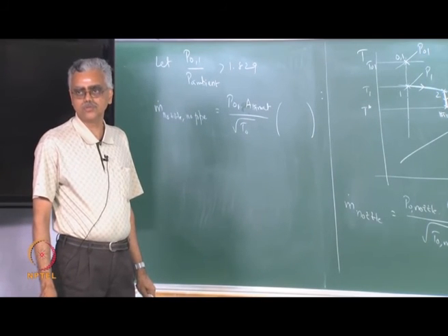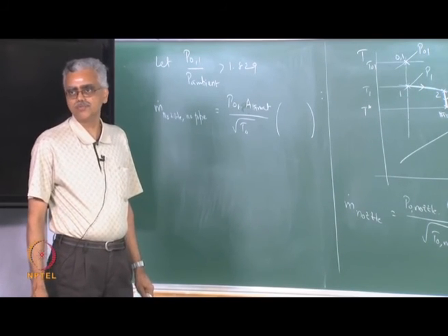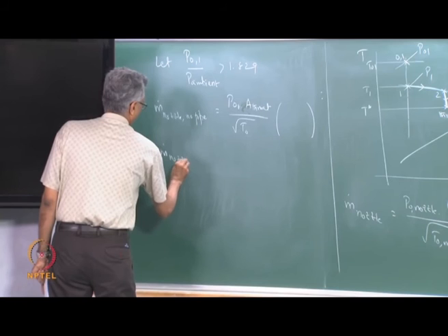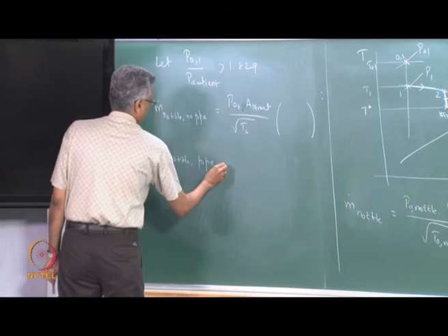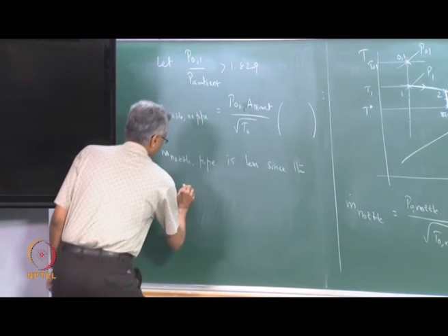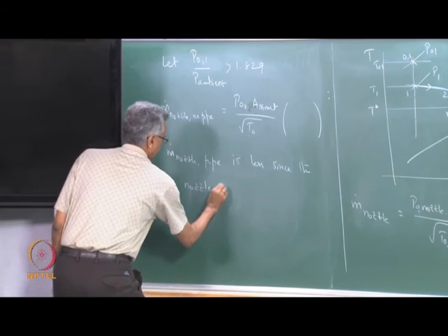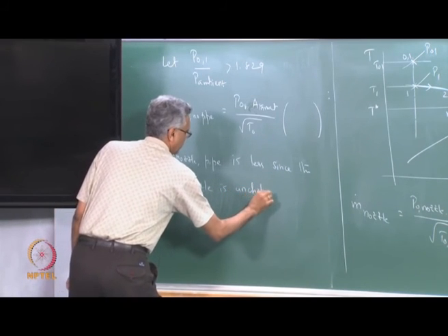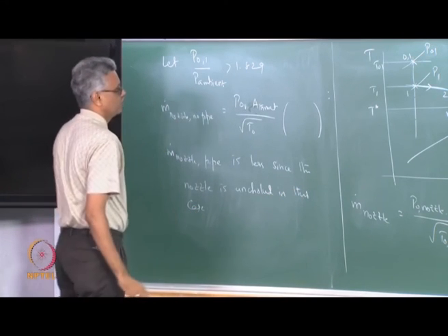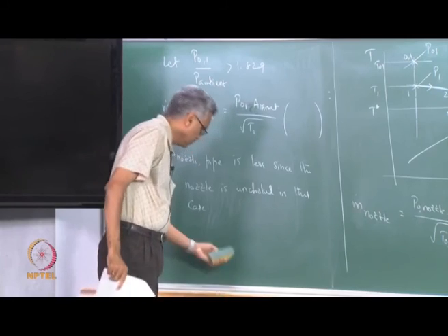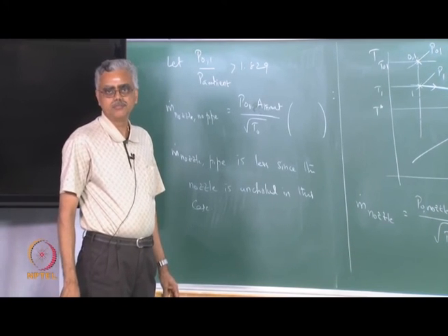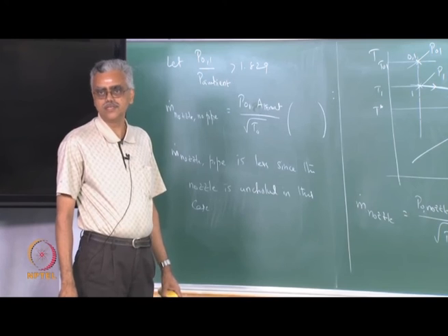That means the mass flow rate through the nozzle is going to be less than what it was before, correct? So, the nozzle is choked if the pipe is not connected. Connecting the pipe unchokes the nozzle so that the mass flow rate decreases.